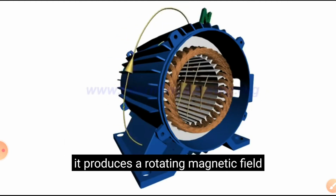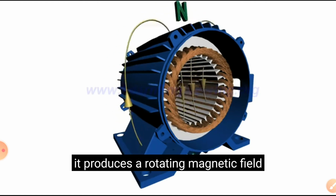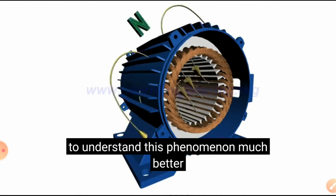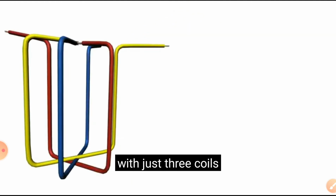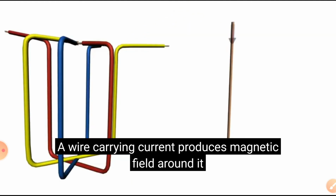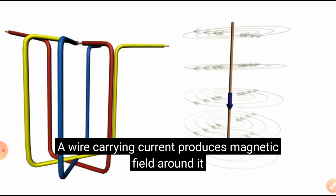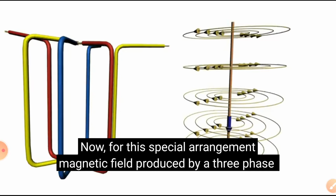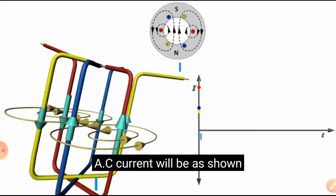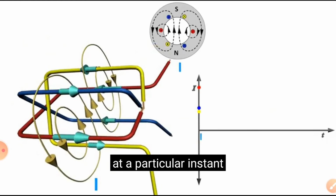When a 3-phase supply is given to the stator, it produces a magnetic field rotating at synchronous speed. The R phase, Y phase and B phase are placed 120 degrees apart mechanically and electrically. Then we know that theta electrical equals theta mechanical into P by 2.